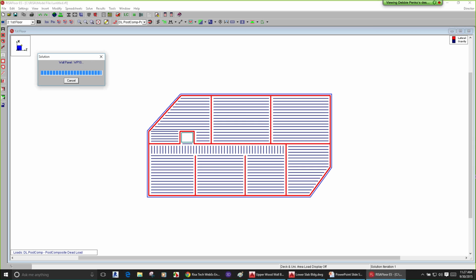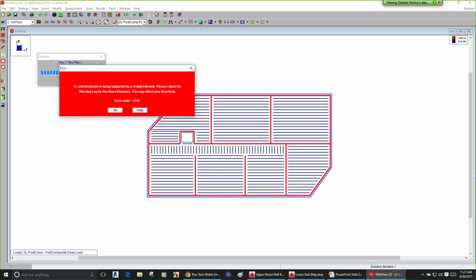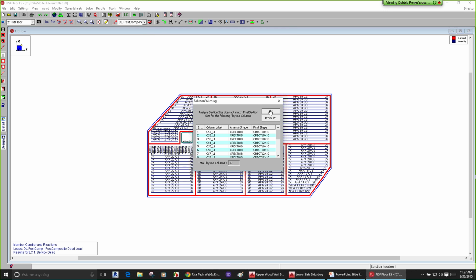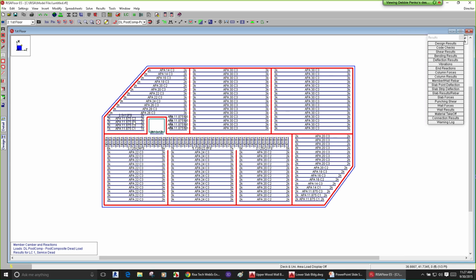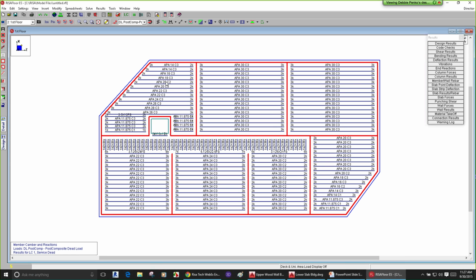So we should see design in all of our wood. We should start to see some reinforcement design on the lower level. Obviously, it's not to the level we want yet because we're going to be adding 2 more floors above it, but it helps us get past that stuff. So looking at this floor level at the wood structure, we can see, got it. We've got some I-Joist design here, which is what we were looking for.